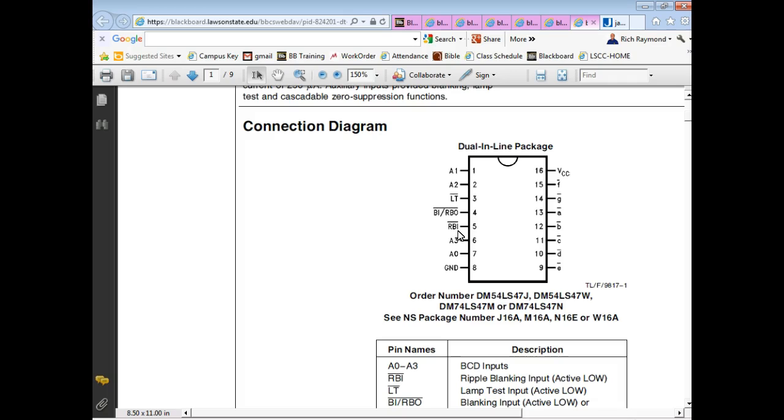They're multiplexing. So what they do is they blank 4 of them, and then they put the data on for 1 of them. Then they blank it and put the data for the next, and then the next, right? Y'all follow what I'm saying? It's doing it so fast that your eyes see them on all the time, but they're not. So snap a picture of your cable box, and if you only see one or two of them on, it's multiplexed. If all of them are on, it's not multiplexed.